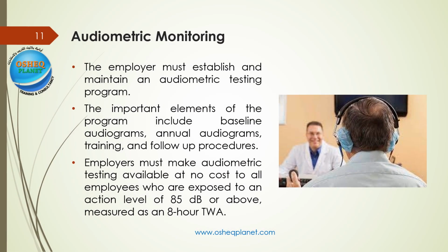Audiometric monitoring. The employer must establish and maintain an audiometric testing program. The important elements of the program include baseline audiograms, annual audiograms, training, and follow-up procedures. Employers must make audiometric testing available at no cost to all employees who are exposed to an action level of 85 decibels or above, measured as an 8-hour TWA.